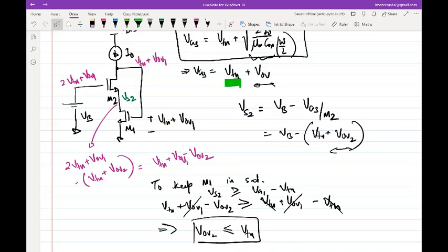Yes. If you keep VOV2 exactly equal to VTH, then otherwise it will not be. That essentially gives you the handle on how to keep M1 away from the edge. I keep VOV2 lesser than VTH by, let's say, 100 or 200 millivolt, then M1 will be away from the linear region and comfortably in saturation with some margin.